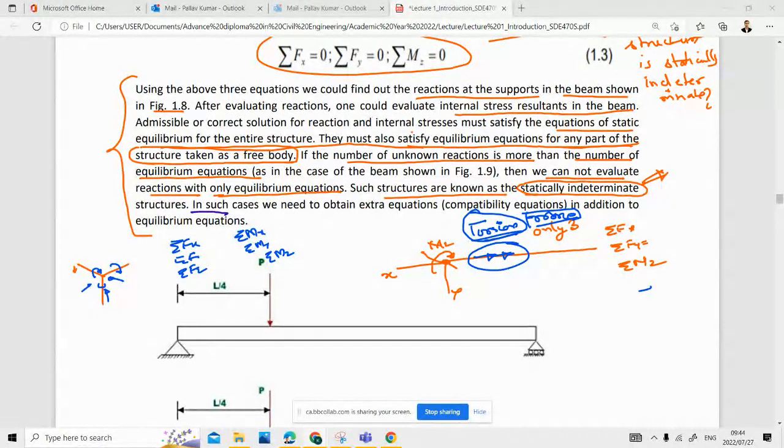In any frame member. Okay, and to get these unknown forces, you have available equations, right? So those are summation of Fx, summation of Fy, and summation of Mz in case of your 2D frames. But if it is 3D frames, you have six available equations. So if with the help of six available equations you are able to solve the frame, your frame is statically determinate. Well done. I am proud of you, Tom.